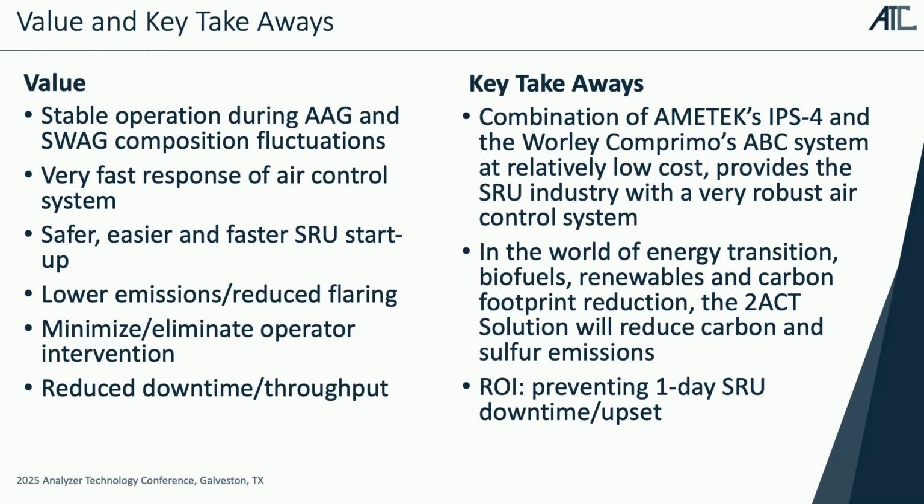So, in the end, because of this, like I said, we're able to operate closer to the optimum set point of the plant. So this would reduce emissions, or in case of severe upsets, reduce flaring. It also reduces the wear and tear of the equipment.